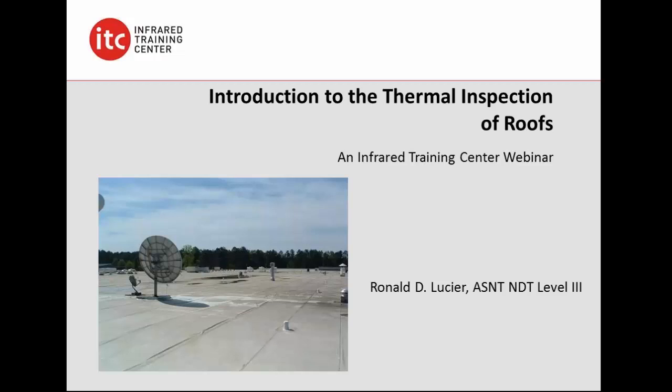The application of using IR thermography on low slope roofs is quite an old technology and probably one of the more complex ones. Most people in our classes, when I've polled folks as to what their applications are, tend to look down on the roofers a little bit. Geez, you bought an IR camera and all you do is roof scans. Well, let me tell you, how dare you? Folks, that's one of the more complex applications of IR roofing because it really involves an awful lot of science. You have to be there at the right time, and you really have to understand the physics of roofing, how the roof stores heat, how it gives it up, and when to be there.